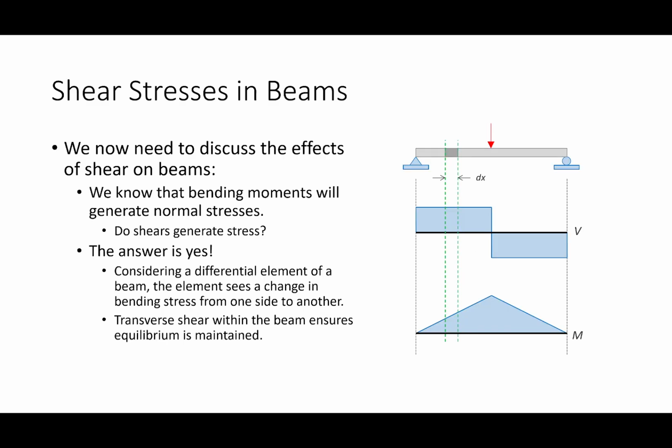Okay, so you have a beam, you take that beam and you apply force to it. Everybody here knows that you can develop from that a shear diagram and a moment diagram. This whole time, we've essentially been drawing the shear diagram and moment diagram, and really what we've been doing is using a lot of shortcuts in the spec to calculate max shears and max moments, but everybody remembers this, right? For the purposes of our design over the past couple weeks, really all we've been focusing on is this. We do a cursory discussion of the shears, and we find that this shear is 30 kips, but the beam can hold up 200, and then we said, let's just move on.